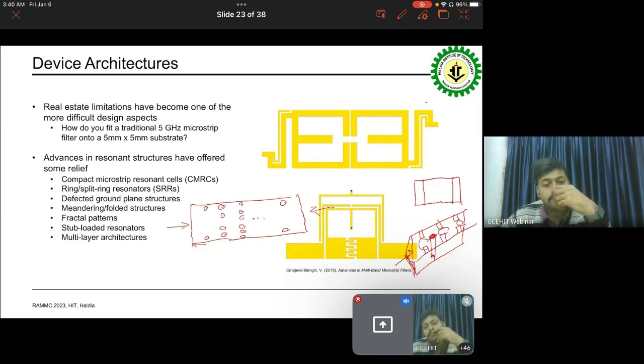Same concept, I can remove these vias and put large inductive posts in here, which ultimately are going to end up being vias. But I typically don't like that topology, because via diameter for the thick film process especially is a lot tougher to control, and here that via diameter for these inductive posts is critical. So I typically try to avoid that design, even though I have set the software up to be able to do that if we need to at some point in the future.